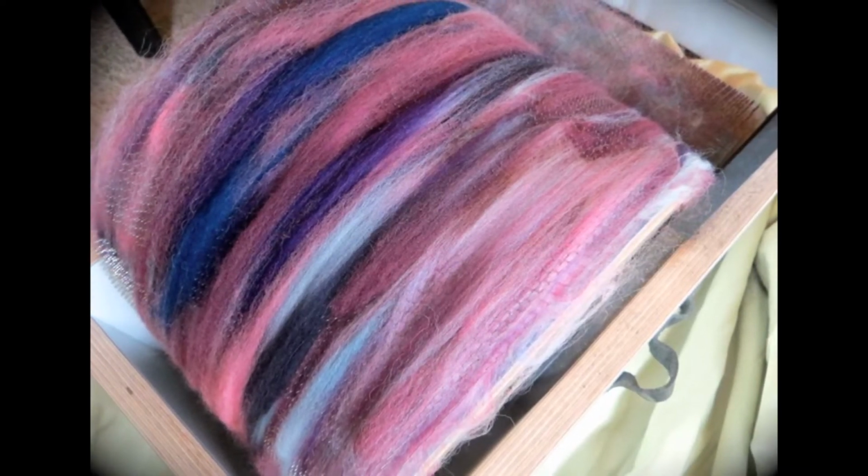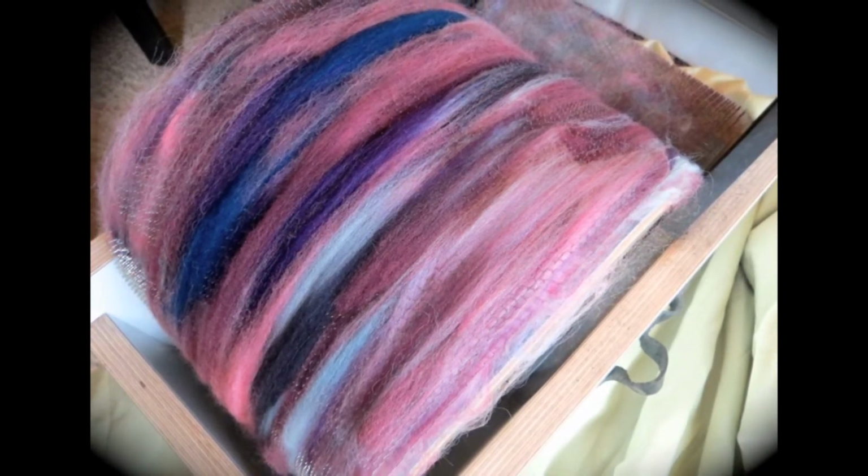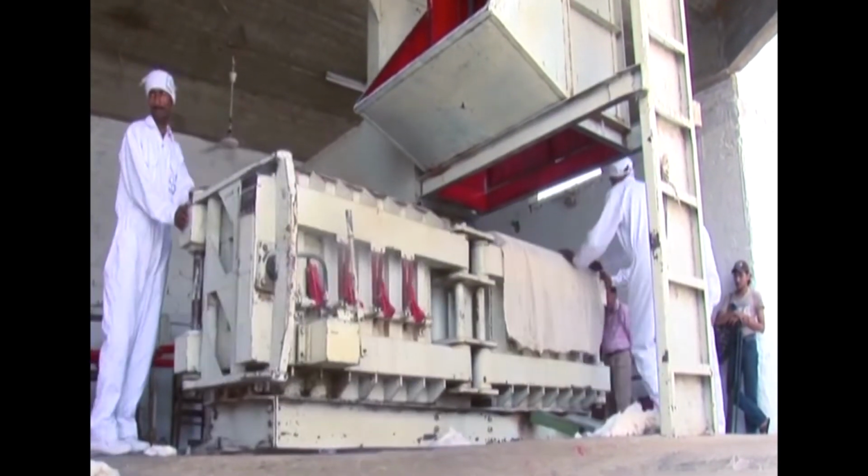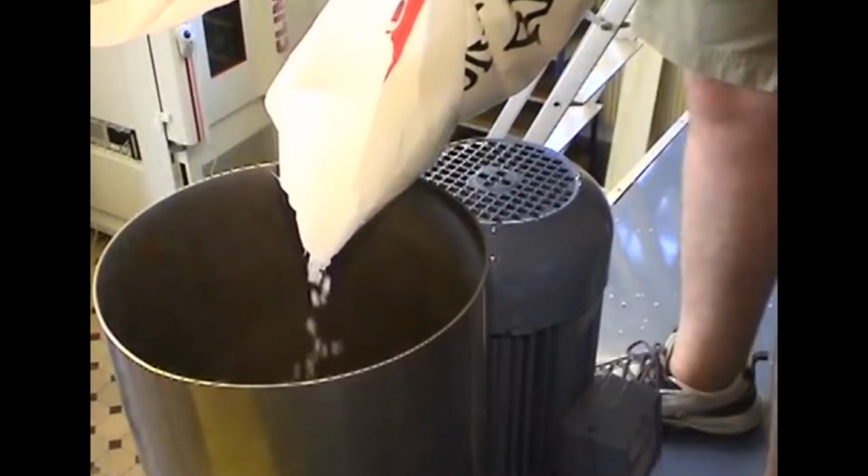Unless it is blended with some other fibers, they are all produced in a filament form only. When they are blended with other fibers, they are cut into smaller staple lengths and then blended with the other fibers. These manufactured fibers have different polymers. So, the polymers are produced and they will come to the chemical spinning factories in the form of chips or in the form of powder. And so, these chips and powder should be made in the form of a liquid, and then the liquid should be made in the form of a linear polymer, so that it becomes a filament.